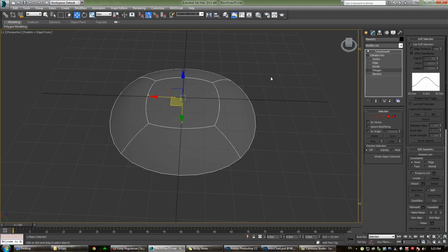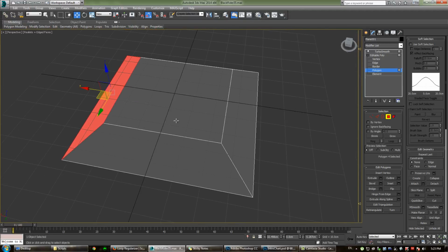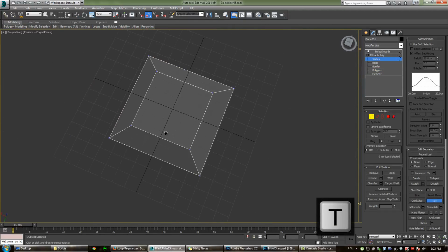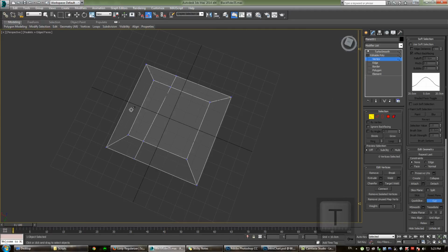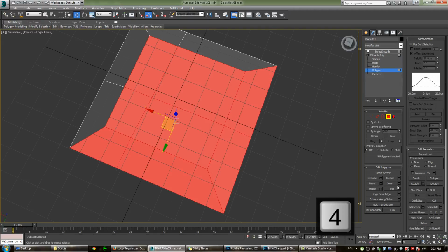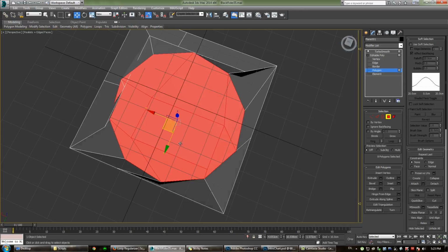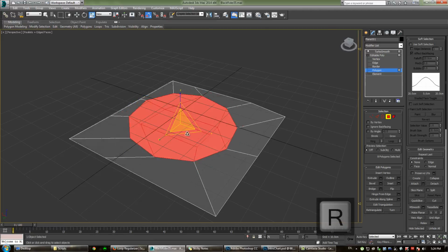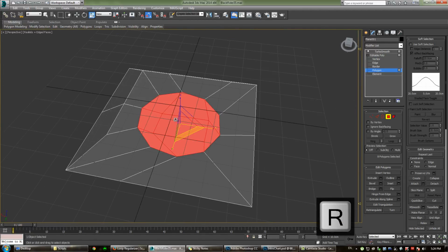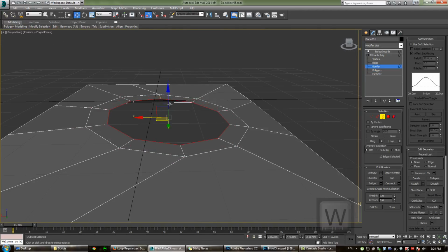Once you've done that, you'll see that I've got the ability to, what this tool does is it creates a perfect circular face out of the selection you have. And it doesn't matter how many polygons you have selected, it will still make a completely clean version of that. So let me just add a little bit of information to this object. Now if I select all these points, which are completely random, and I use that inset tool, which is what we were using last, now if I right click, I can click regularize, and it's going to create a perfect circular inset of that, which is extremely useful, you'll see later on, for when we want to create holes for bolts and things like that.